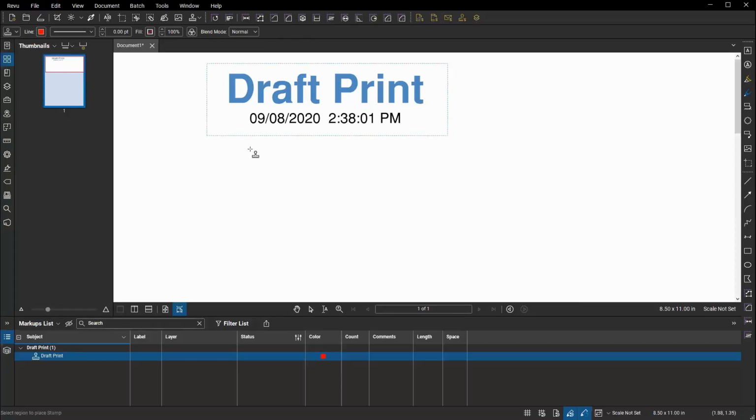You can also scale the stamps as you're placing them. I'm just hitting a single data point, which makes it come in at its originally created size. To make it smaller or bigger, you can click and drag it and place it dynamically to the scale value you want, and it'll adjust everything to fit within those particular parameters.